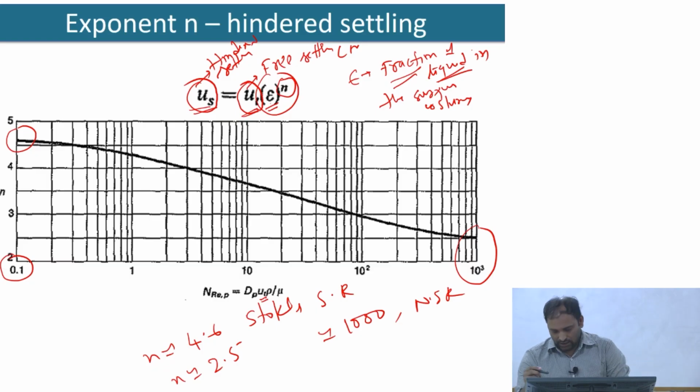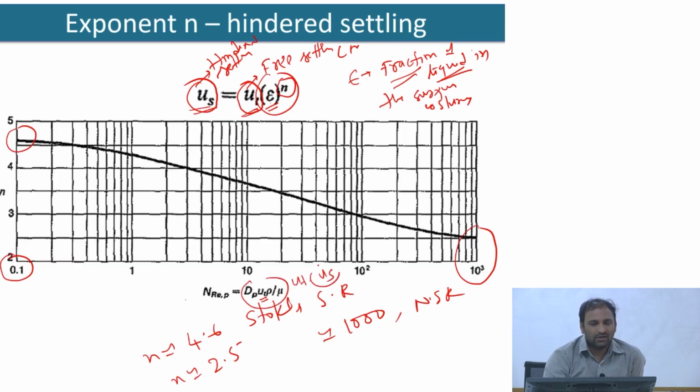So typically, if you look it up, let me just do it. In one of the examples, we have a case where we calculate the free settling and hindered settling velocities. Of course, it is slowed down, but not by a large amount. So in that context, whether you take UT here or US is not going to shift your Reynolds number by a large amount. Maybe we'll comment on it when we do the...